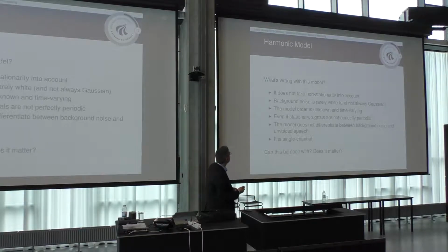So what's wrong with this model? Well, anonymous reviewer number 1 might argue that it does not take non-stationarity into account and speech is continuously varying. You might say, well, I don't think the background noise is right, and I don't think it's even Gaussian. You might say, well, the model order, so the number of harmonics here, is unknown and it's time varying. And even if the signal was stationary, the signals are not perfectly periodic for unspecified reasons. And the model does not differentiate between background noise and non-noise speech, and it's single channel. In many cases, you want multiple channels.